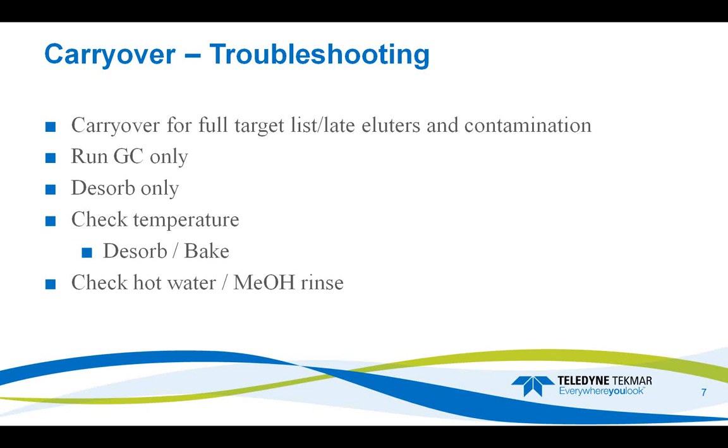If we do not see our carryover coming during desorb only, then it's likely that our carryover issues are on our water handling side. And so at that point, we would want to check to make sure that we are adequately rinsing so that our water is hot, make sure our heater is working properly, make sure that we're actually transferring the water during the rinse cycle, and then maybe consider adding a methanol rinse if available, or maybe increasing the number of rinses, both water and methanol, that we use.